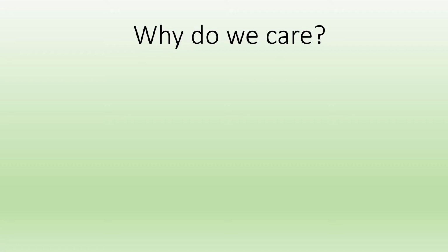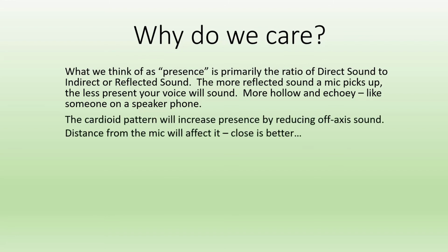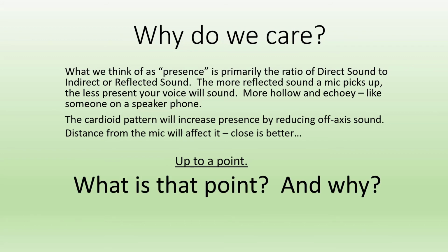Okay, why do we care about polar patterns? What we think of as presence is primarily the ratio of direct sound to indirect or reflected sound. The more reflected sound the mic picks up, the less present your voice will sound, the more hollow and echoey, like somebody on a speakerphone. The cardioid pattern will increase presence by reducing off-axis sound. Distance from the mic will also affect it. Closer is better. Up to a point. What is that point and why?